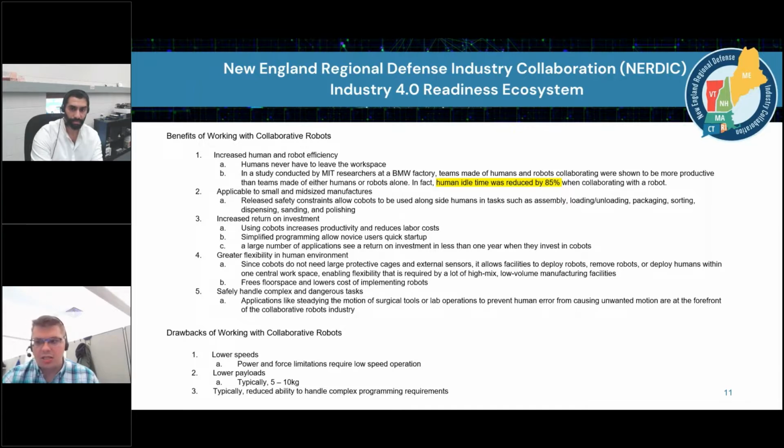So the cobot in this case could then function either way, either simplified programming, usually through a graphical interface, or through the more traditional coding style that industrial robots are accustomed to. So it's just a key point to be aware of, especially when it comes to the lower cost cobots that do not have industrial counterparts within the same brand. It's just something to be aware of, that it could be an issue.